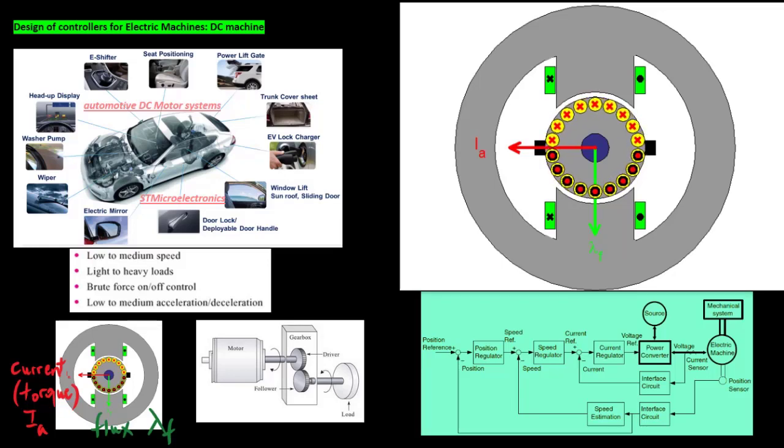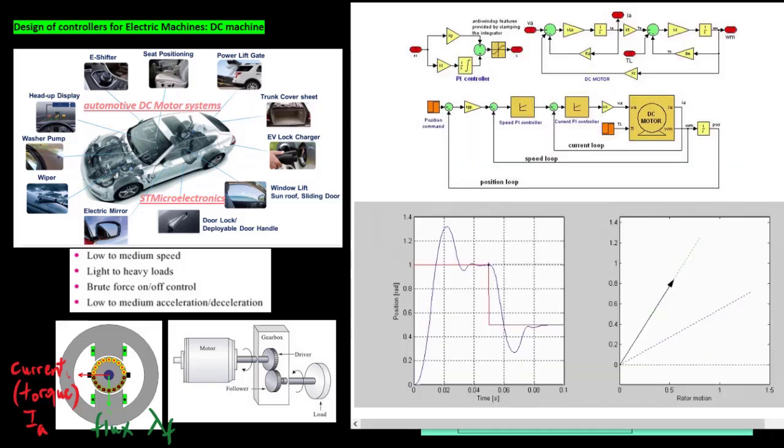The torque of an electric machine occurs through the interaction between the flux linkage and the current. Usually, the flux linkage is kept constant by the permanent magnet, or constant field current. Also, the electric machine can be modeled as a converter that converts the current to the torque or to the thrust force. The rotating speed of the electric machine is decided by the torque, friction, the load torque, and the inertia of the rotating part of the system under control.